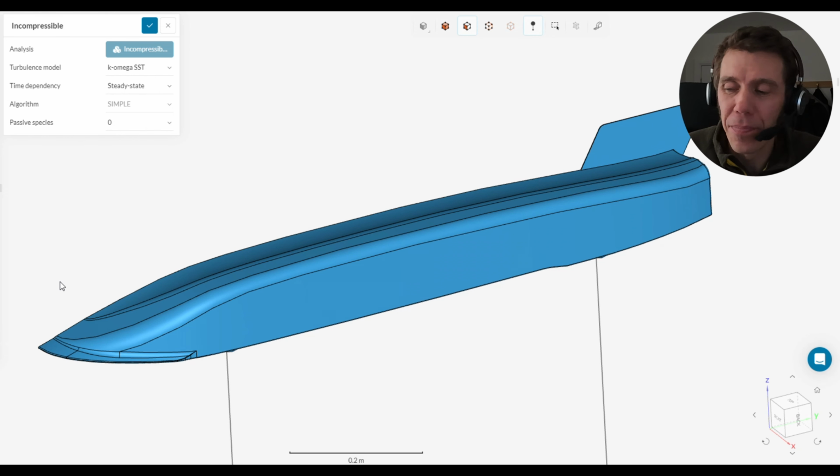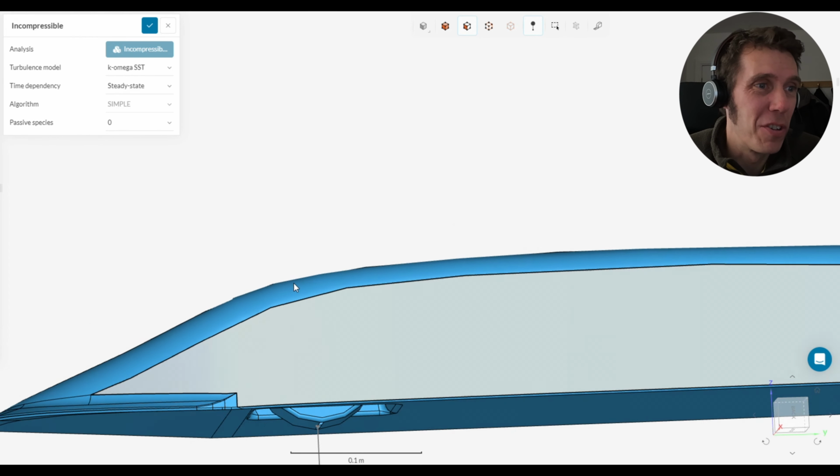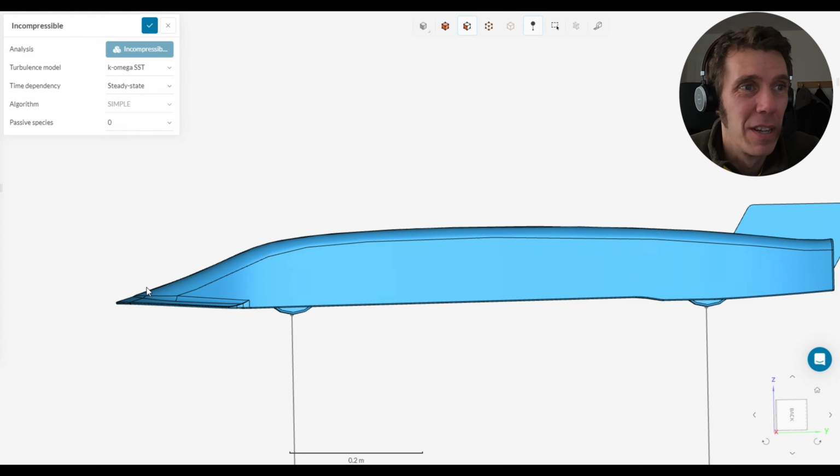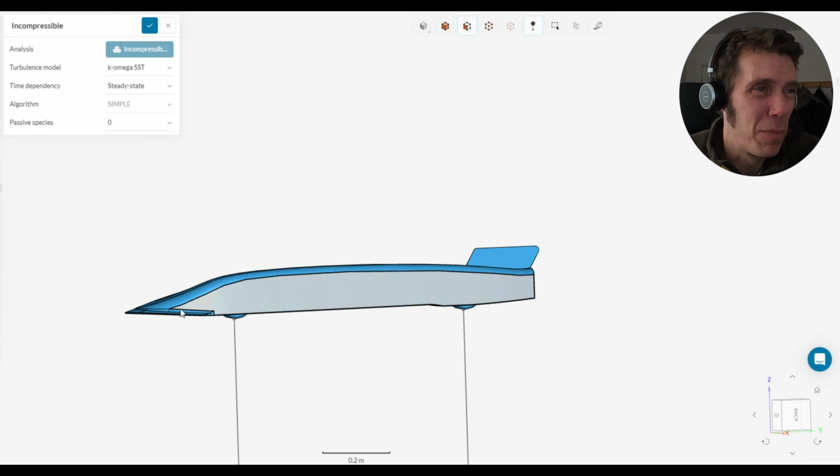So early on with the design of this body shell, I decided to have a slightly higher ride height at the front of the car than in the area of the wheels and tyres. Early on, I had I think a 10mm ride height at the closest point, and an extra 10mm to the tip of the nose, just to give a bit of an allowance for any surface imperfections, and maybe the car getting bumped at the rear and causing the nose to come down lower, which I think was happening with my Cone Mark 1 car. So that explains my design choice there.